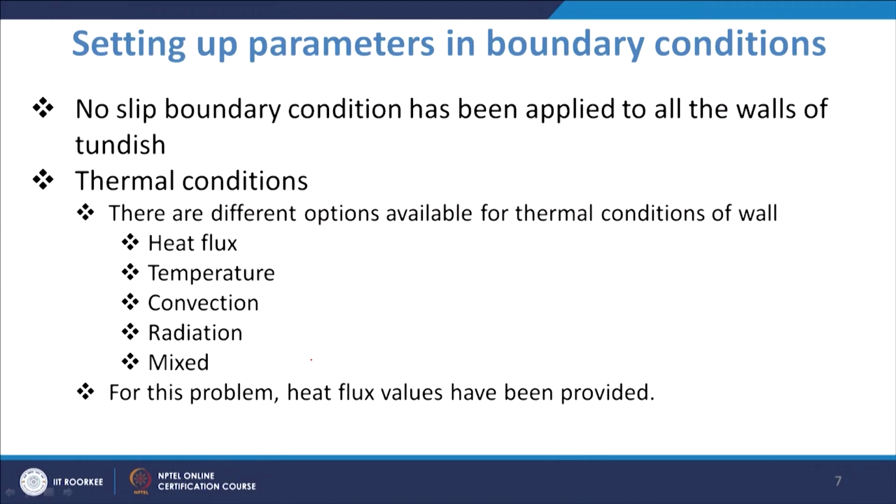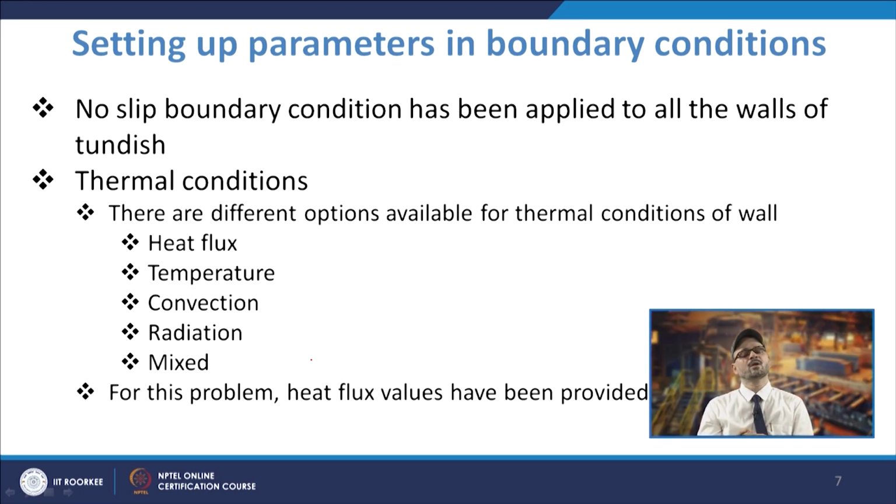So, from there you can have these heat flux values that you can take, and that will be required to study the temperature distribution, how the temperature changes. Now, as we discussed, when we are applying the boundary conditions, normally on the walls we apply the no slip boundary condition, and we also use the standard log law wall function in the case of the standard K epsilon turbulence model.